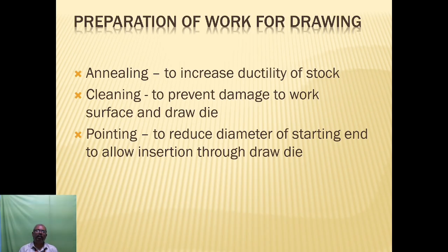When you prepare the work for drawing, you have to use annealing to increase the ductility of the stock. You have to do cleaning to prevent damage to the work surface and draw die, and pointing to reduce the diameter of the starting end to allow insertion through the draw die. So in this lecture we discussed the bulk deformation processes. First we discussed rolling, then extrusion, then we discussed forging, and finally we discussed wire and